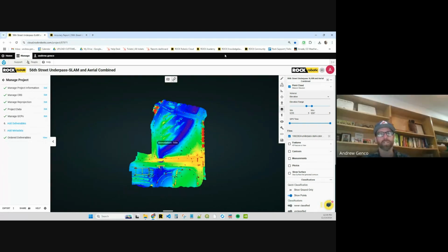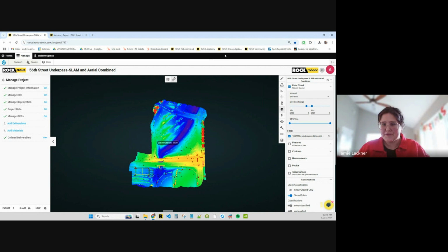Yeah, in regards to that, SLAM capture is best done slowly and purposefully. You imagine you're walking with a walker or something like that. You want very slow, deliberate movements. Think about it like you're bringing in a gallon of uncapped sweet tea. That's how I think of it.